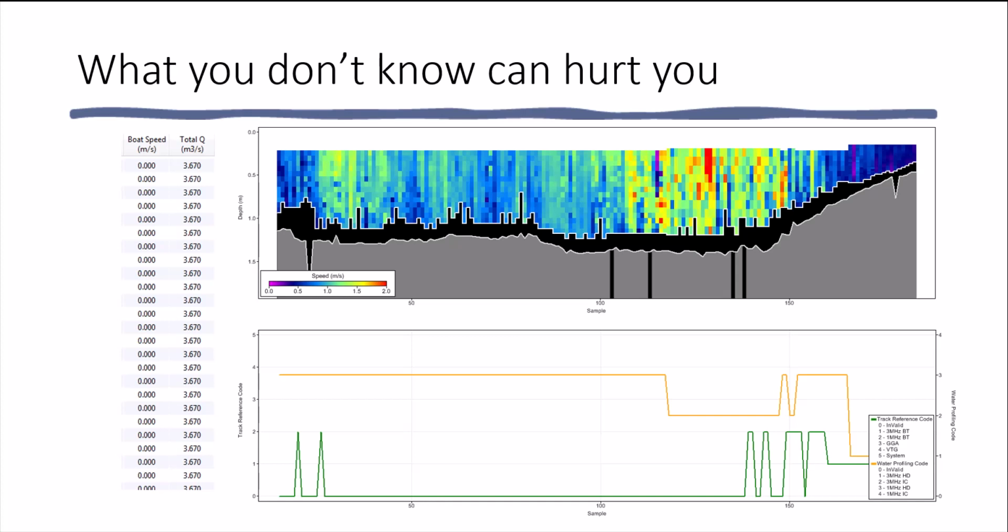So what velocity is plotted for samples 20 to 140? It is the raw relative velocity with 0 correction for the boat speed because the boat speed has been set to 0. Likewise, because the boat speed is 0, the computation of discharge using the cross product results in a 0 discharge, thus no change in the total discharge.